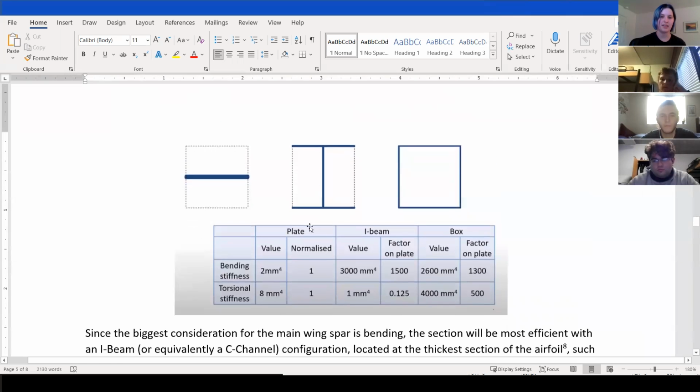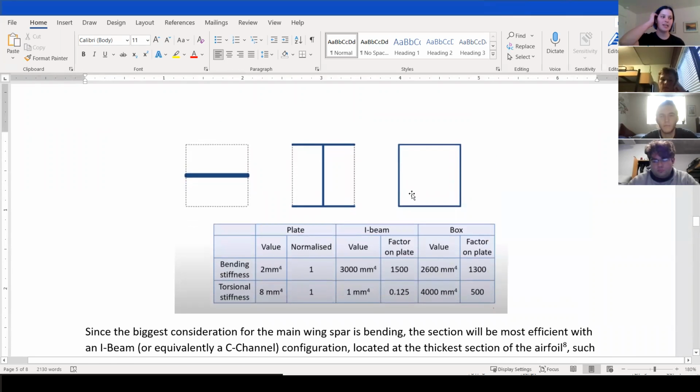Also, if we imagine you're bending, you want to separate those plates in your I-beam. The farther apart they are, the easier they can resist a moment. That's why you want your wing to be thick: the thicker your wing, the farther you can spread that out, and the less weight you need to put into making that I-beam structurally thick.